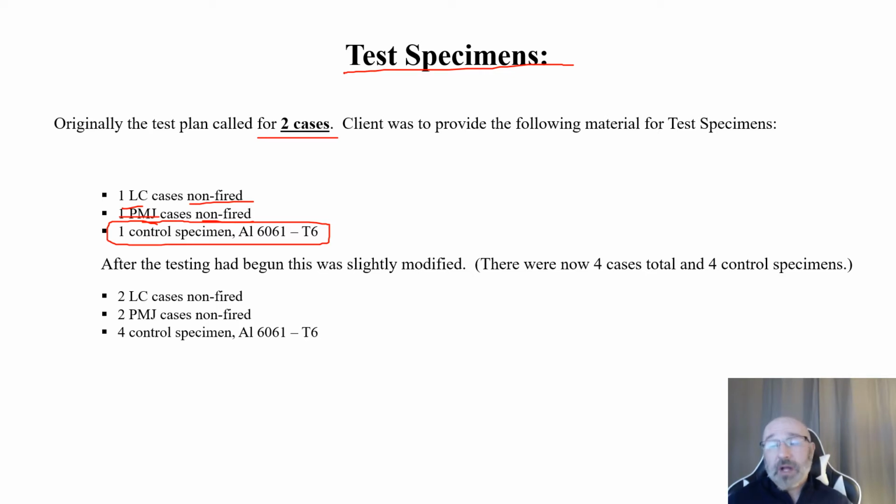If we're talking about running hardness tests and tensile testing, we want to make sure that our machinery is calibrated correctly. And if we've got two different test specimens that we don't necessarily know the material properties of, or what we should even expect, especially when going into this blind as they had wanted us to do, we need to make sure that our system is set up correctly and acquiring the correct calibrated data.